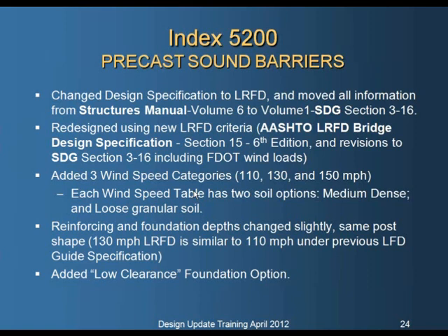Moving on to the precast sound barriers, this was a rather significant change to the design with the release of the 6th edition of the AASHTO LRFD bridge specifications. It added a section 15 bringing in sound barrier design, which used to be under a guide specification using allowable stress and load factor design.